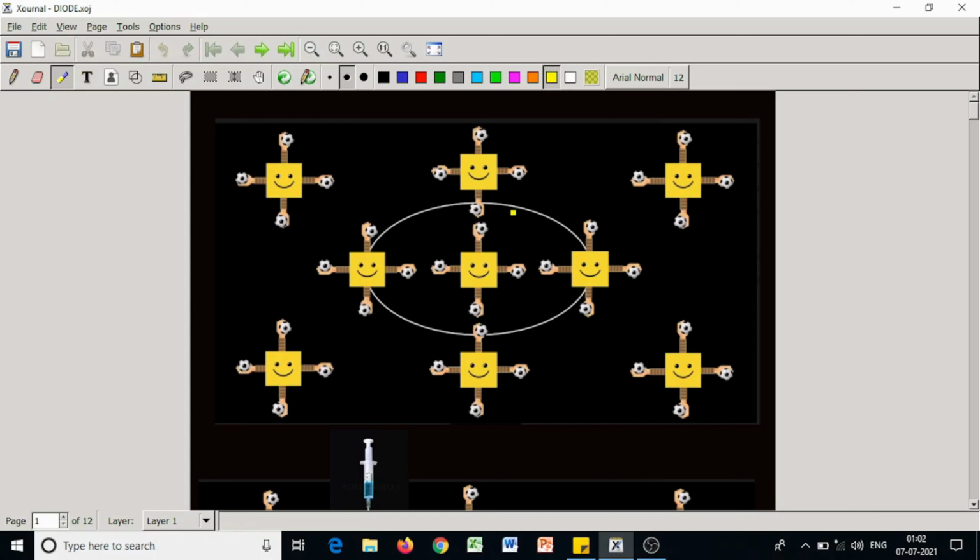The dislodged negative electrons can wander freely in a random fashion, leaving behind a vacant space called a hole with positive charge. Thus, the hole moving opposite to the electron, together with the electron, takes part in conduction of electricity. Opposite to this bond cleavage, or electron-hole pair generation, recombination of electron and hole makes a free electron into a bond electron.